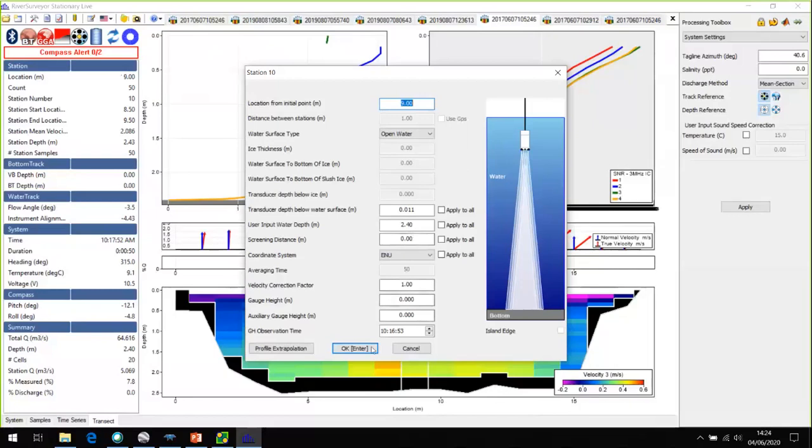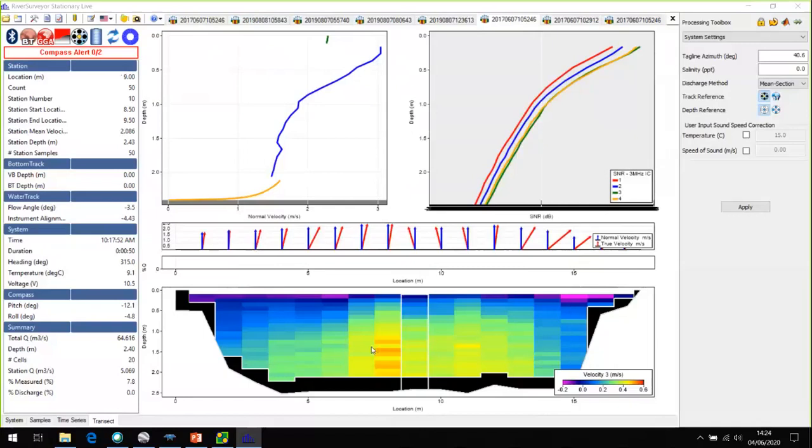You can manually survey the channel afterwards if you want to do a really good job, or you can estimate. Yeah. I came back the day after and did another stationary gauging with the same distances and just applied the change. I applied the depth plus the change in stage between the two to get the real depths for the day. Okay, so that's one thing, getting all the depths.